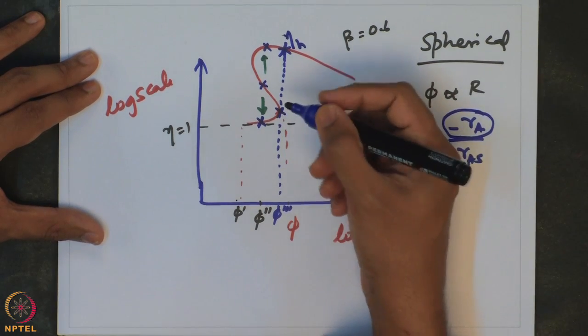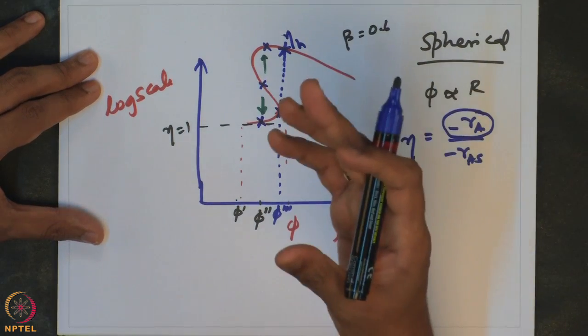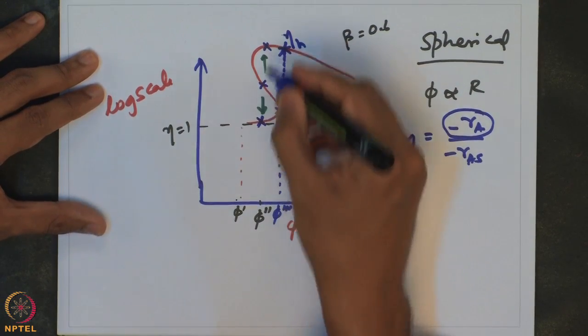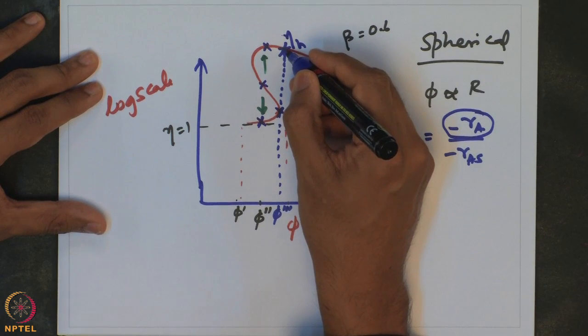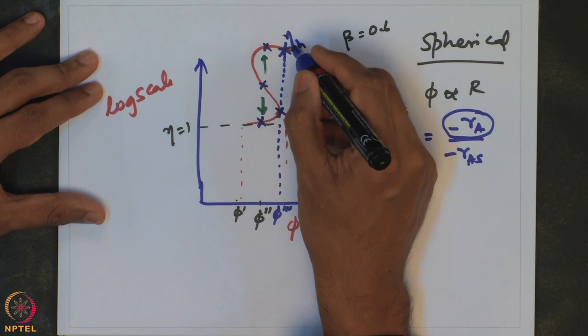And this has a strong implication in terms of the design, because the catalyst which we use has certain properties, and the temperature that can be withstood by the catalyst is limited. So, if there is a possibility of operating in this particular Thiele modulus, then one has to always pick a catalyst such that it can withstand this temperature that may be achieved for this particular rate at which the reaction is happening. Otherwise, there will be a detrimental effect on the catalyst, which could cause deactivation of the catalyst and strongly affect the productivity.